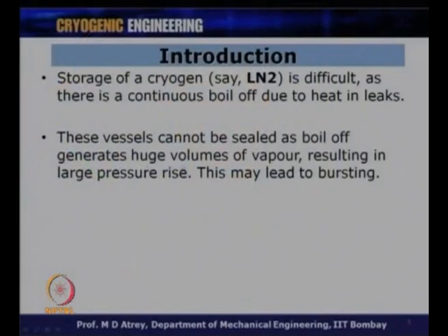These vessels cannot be sealed as boil off generates huge volumes of vapor, resulting in large pressure rise. If I want to enclose everything, and if I say I do not want to see this boil off, and we have a lid on the top, what will happen? Slowly and steadily the pressure inside will start increasing, because the volume of vapor will result in a large pressure rise, and ultimately this may lead to bursting.